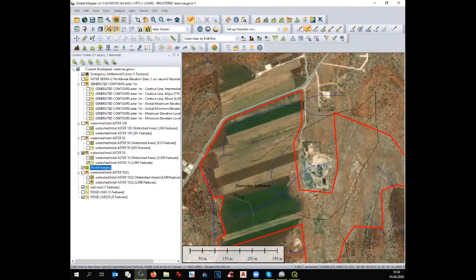Now, your question: the existing road you keep, but if you have to make a new internal road, then try, for example, to use this location here, because here is the highest point. If you do an internal road, try to use the location that doesn't need a culvert, that has the best protection against erosion and water. I don't know if I answered you properly. Can you hear me? Yeah, Andrea, I got your point. So the existing road you keep because you don't want to waste money. But for the new road, try to find the best location.